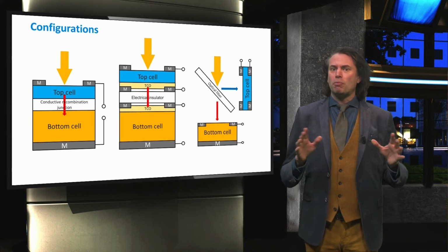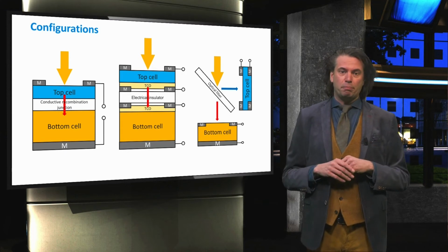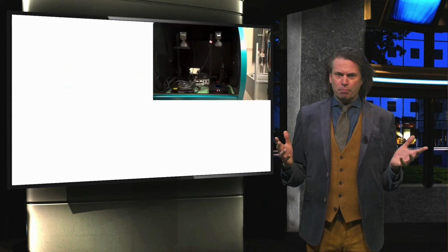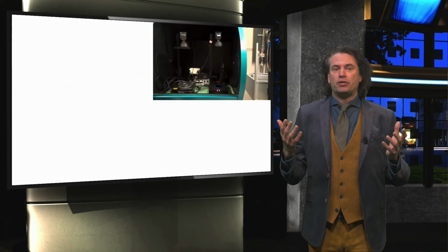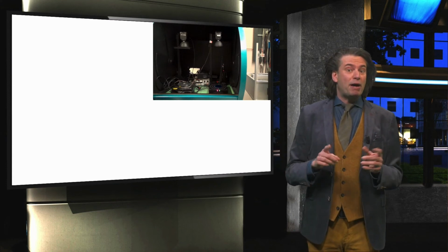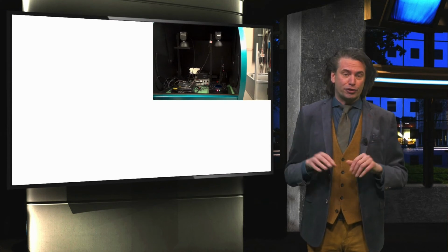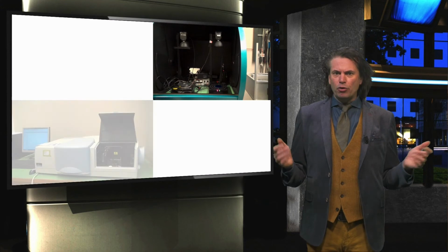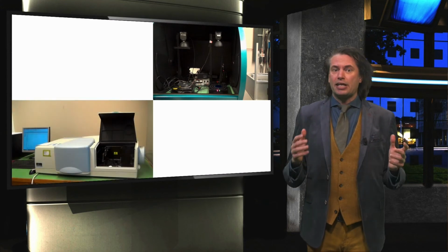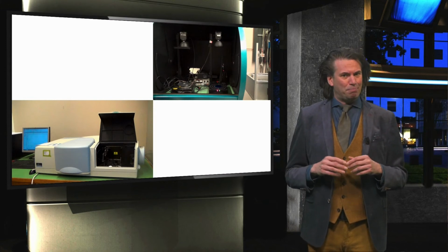We also devoted some attention to the main measurement and processing techniques used in the PV technology field. For the measurement techniques, we looked at the effective minority carrier lifetime, which is a measure for the recombination rate and thereby the quality of the bulk material and how well the surface is passivated. We looked at a typical spectrometer setup that is capable of measuring the reflectance and transmittance spectrum of solar cells and materials. The absorptance can subsequently be calculated.